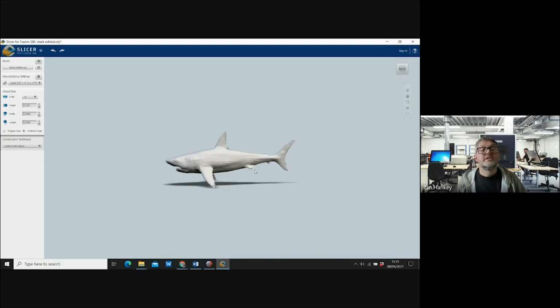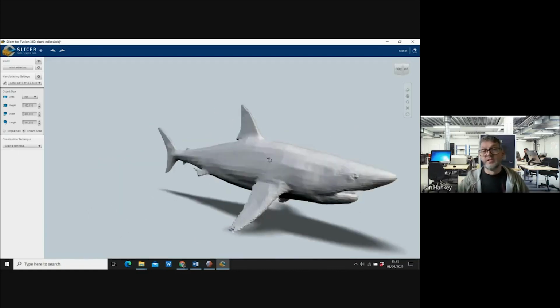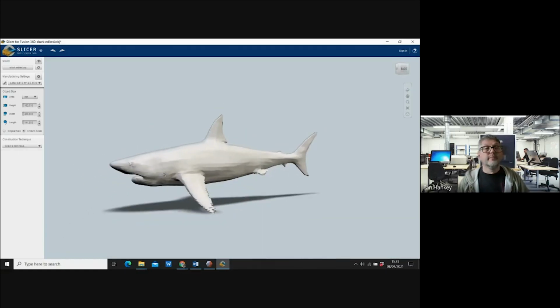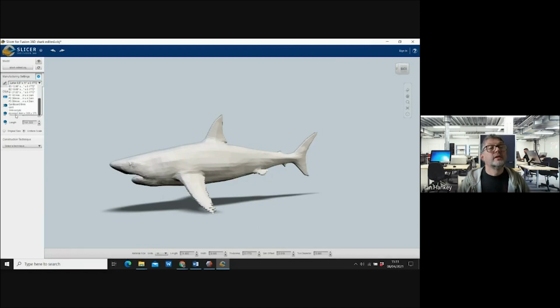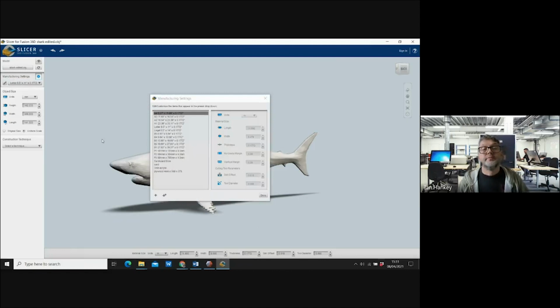So first thing I'm going to do is scale. So I'm going to go to my object size. It's inches, make it millimeters, and then the width, which is 203, I'm just going to type in 400, and then just click anywhere in the grey area, and now that's changed my scale. Right. Next thing to do is go up to where it says letter, and drop down here, and then go into edit. And I'm going to click plywood as though I'm actually setting it up now.